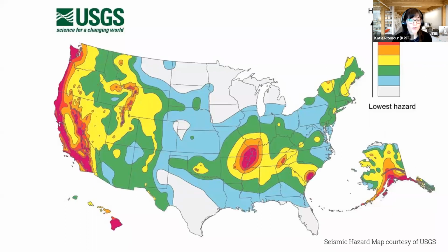Seismicity also plays an important role when looking to use mass timber as your lateral system. It obviously will impact the extent of walls you will need and the fiber quantity in those walls. It will also influence the code path that you have available to you as you look to permit the building, and it will also influence the conversations that you have with those jurisdictions. For example, low seismic regions may be more open to these new materials and these new lateral systems than a high seismic region. So you can definitely take that into account when looking to incorporate these in on your project.